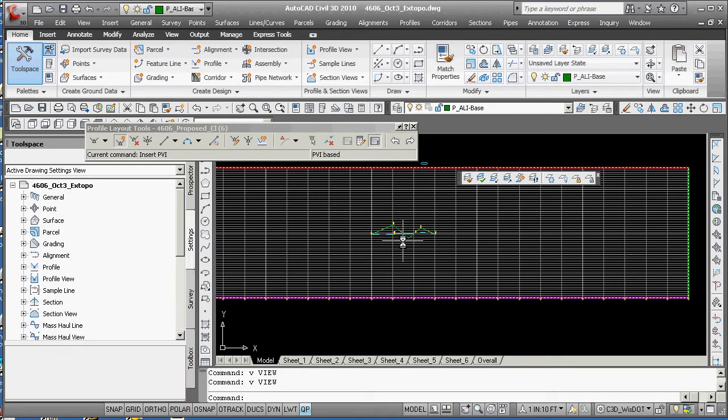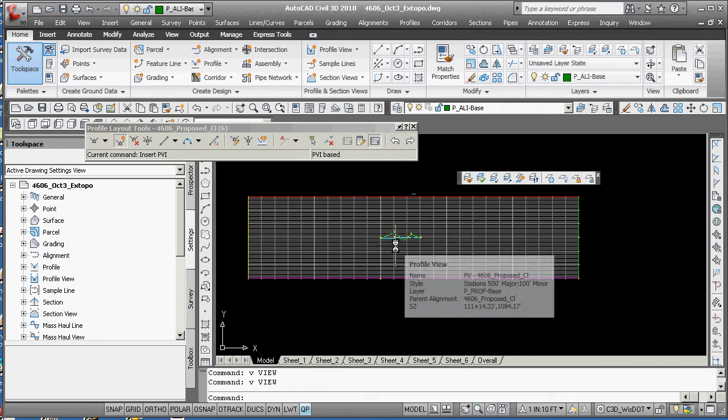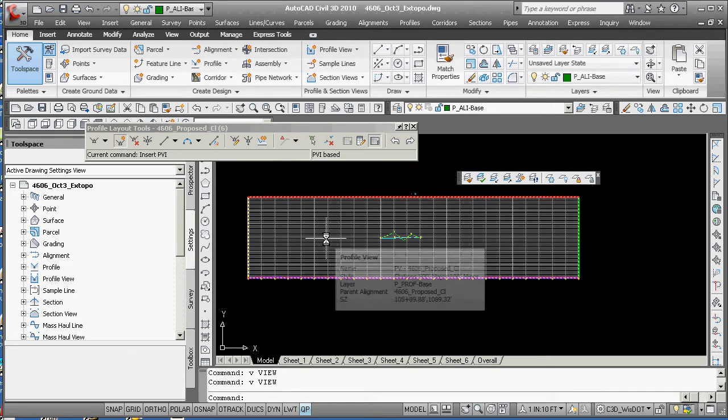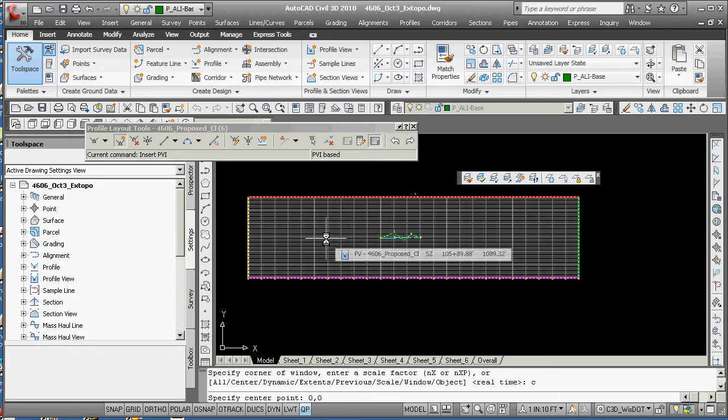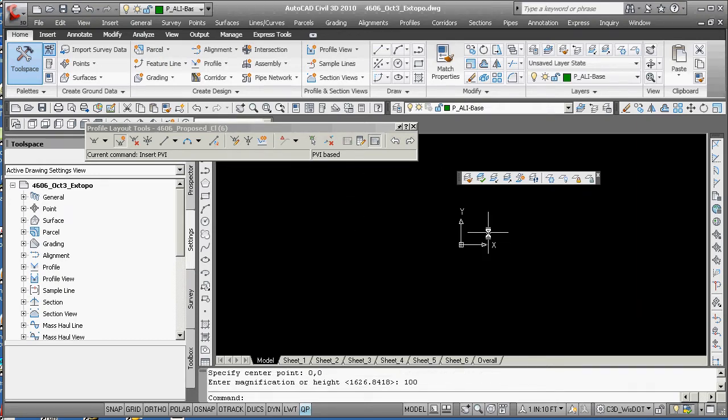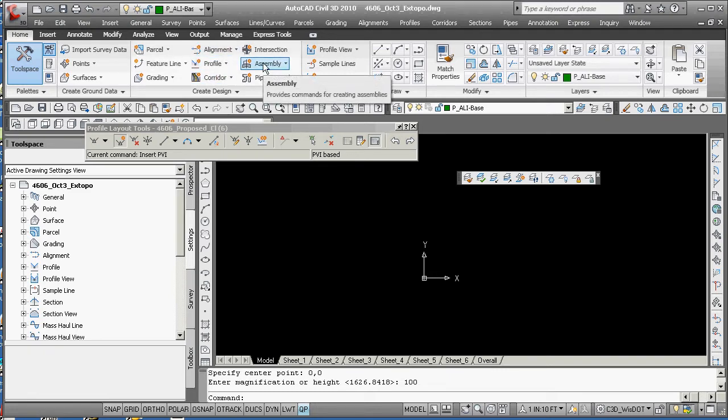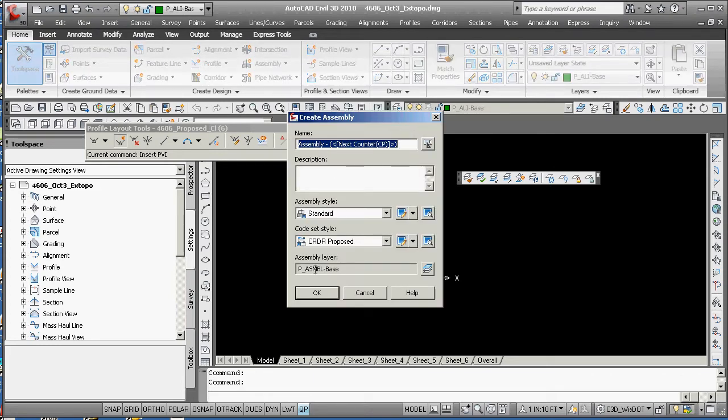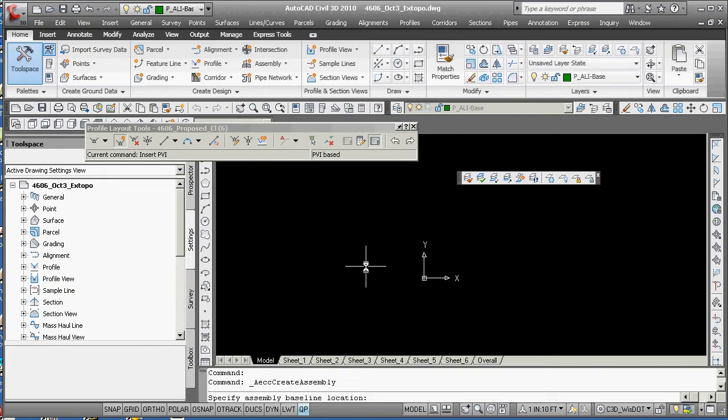At this point in time, you are ready to go down to the 0, 0, so zoom, center, 0, 0, at a height of 100. Now you're down on there, and you want to now make an assembly. When you create an assembly, you're going to get this interface. That was the whole point later on. You're going to hit OK here. And where do you want it? You'd probably want to put it not at the 0, 0, but 20 up. You see something like that.